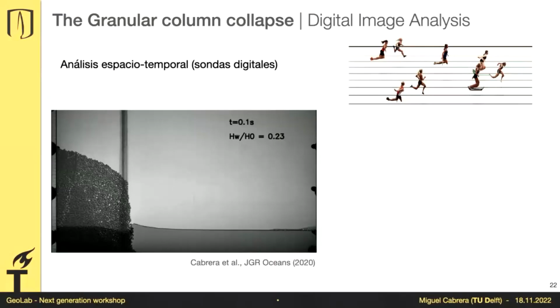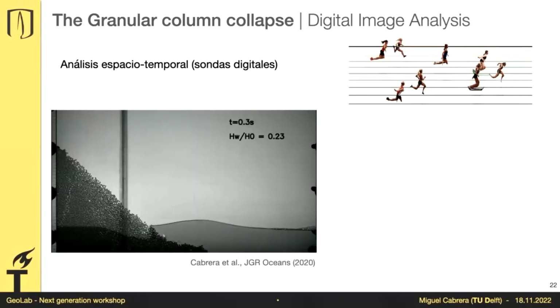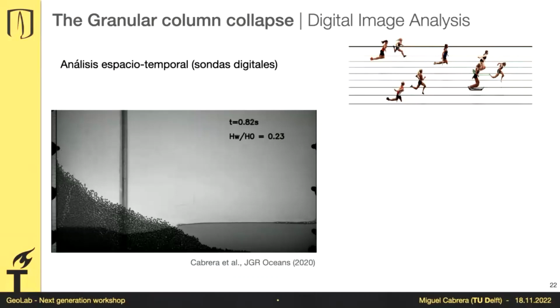So the spatiotemporal analysis, or the cameras they use for the Olympics, are not the regular cameras we have with the sensor that goes like a matrix. It doesn't go X pixels wide, X pixels high. They only take one line of pixels, and they take that line of pixels over the finish line. That's why the background is white. If you recall from the Olympics, the track usually has a color, blue, green, or orange. But they place that line of pixels right at the finish line.